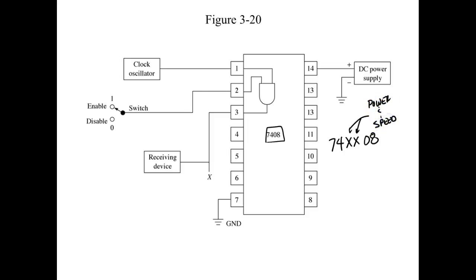And so what I was saying, if all you need is the pin out, you could look up any 7408. So a 7408, which is the standard, would have the same pin out as the 74S08 or the 74LS08 or 74ALS08 or the 74AC08. They would all have the same pin out. Now, if you're trying to figure out what this guy right here can drive, and what's a legal high and what's a legal low, you'll need to look that information up, right? You understand?